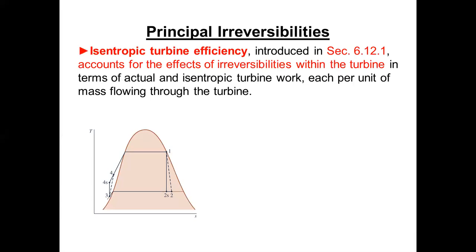We have what we call labyrinth seals between stages and on the ends of the rotor. And unless those things have been wiped, and we'll talk about what that means later, there's very little steam loss through the seals. And so thermally, the thing's extremely efficient. But we need another type of efficiency to describe the steam turbine, and that is the isentropic efficiency.